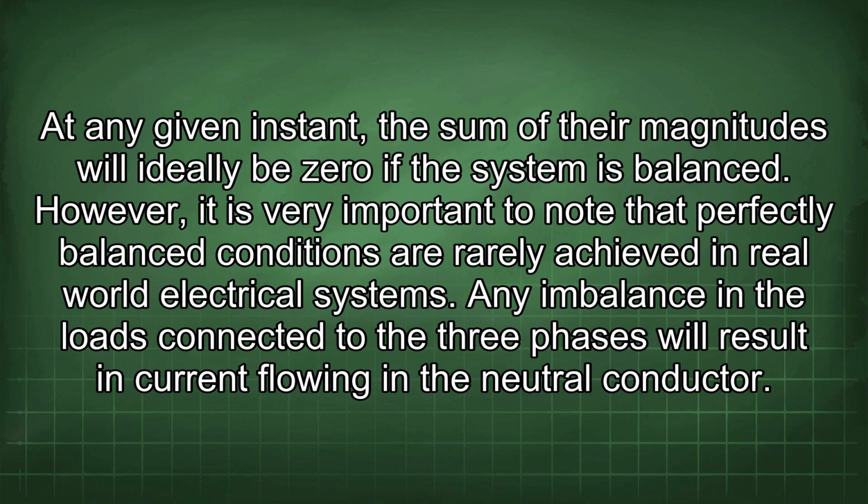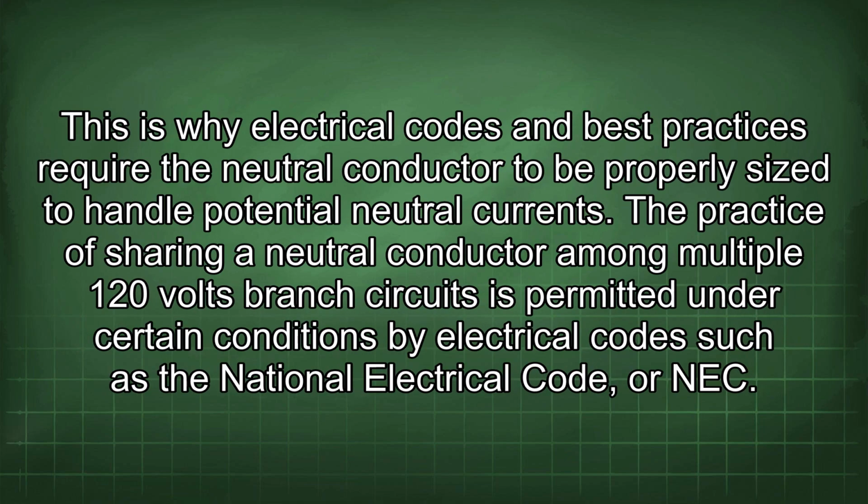However, it is very important to note that perfectly balanced conditions are rarely achieved in real-world electrical systems. Any imbalance in the loads connected to the three phases will result in current flowing in the neutral conductor. This is why electrical codes and best practices require the neutral conductor to be properly sized to handle potential neutral currents. The practice of sharing a neutral conductor among multiple 120 volt branch circuits is permitted under certain conditions by electrical codes such as the National Electrical Code, or NEC.